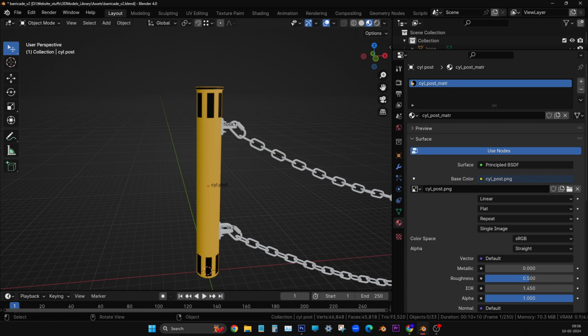Close the box, right side. Go to the material data block, that white color globe icon. Now you choose that closet material only. Closet material. Yeah.